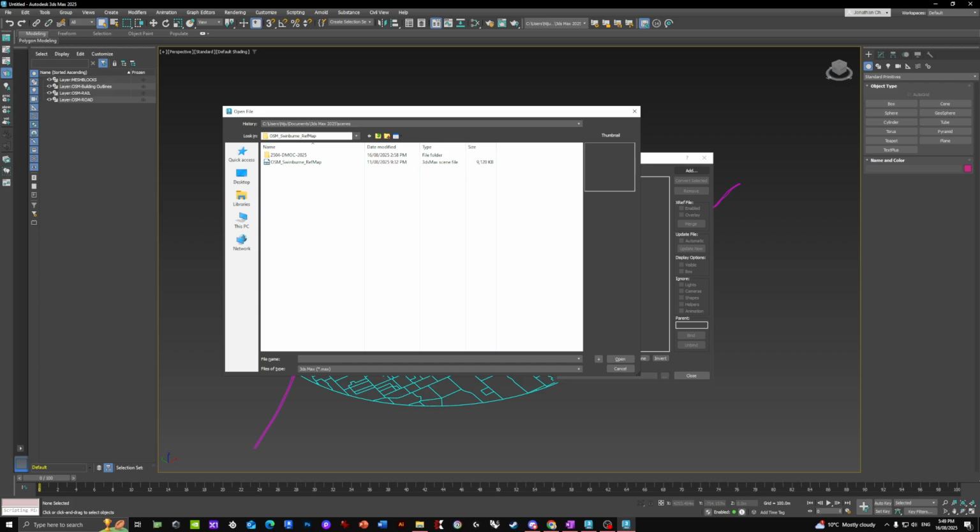Using this method keeps the two files separate, so we can work on our own file instead of adding or changing this base file. It's pretty good when you're doing a project with others. He's doing his own 3ds file, you're doing your own, but you need to combine each other's. So this is a good method to use Xreference.